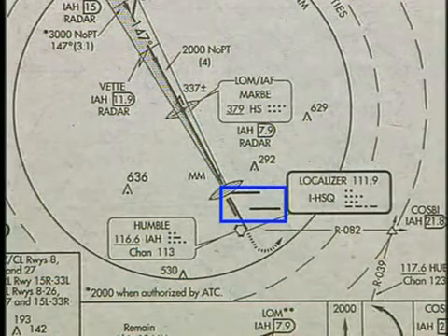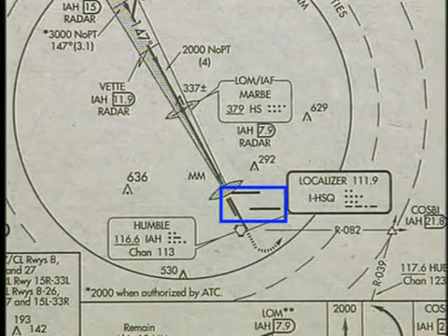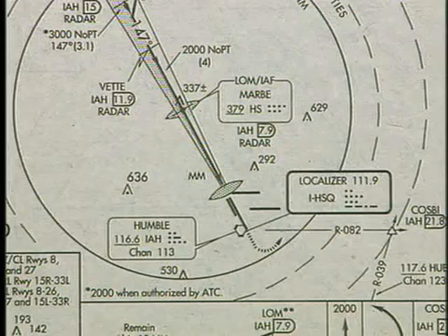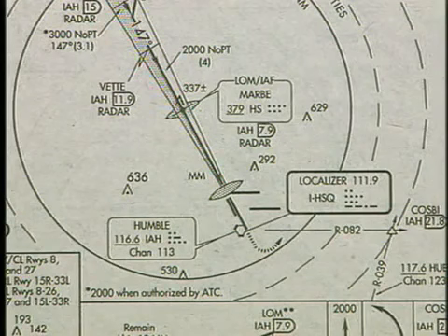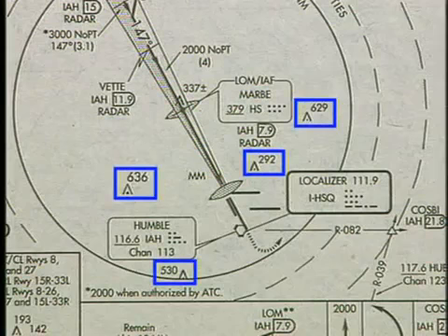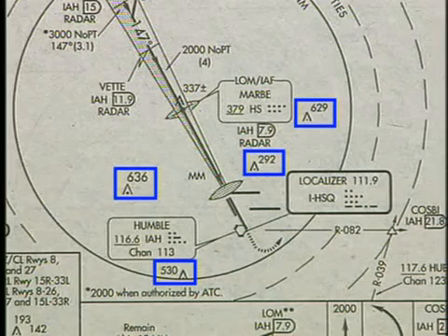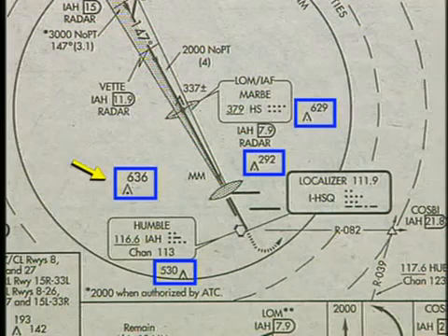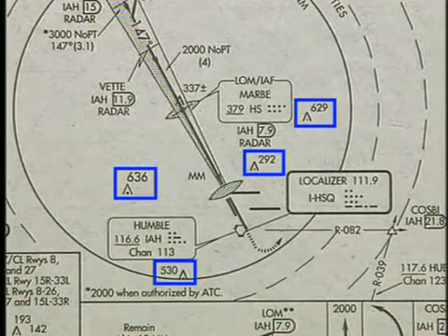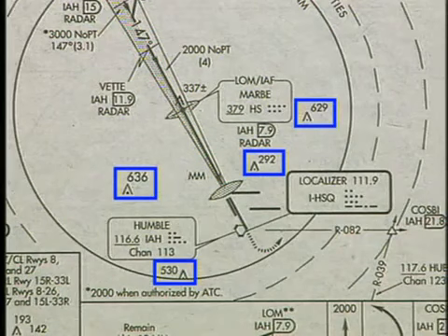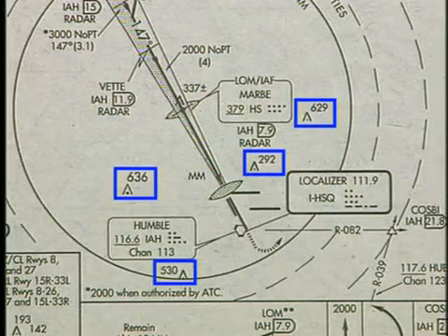A bold diagram of the runway layout indicates the primary airport. Typically, other airports in the vicinity are not depicted on NACO charts. Obstacles or spot elevations are shown with their MSL heights. The symbol for the highest obstacle or spot elevation contains a bold dot and an enlarged altitude number. This information is for reference only and must not be relied on for terrain clearance.